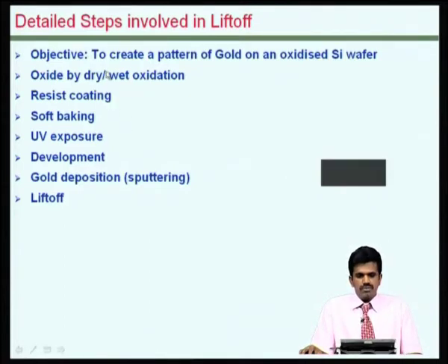In the case of Liftoff, what we need to do is basically to coat the resist. But what we normally see in practice is that the gold does not adhere well with the silicon, and in many practical applications you do not actually put gold onto the silicon.